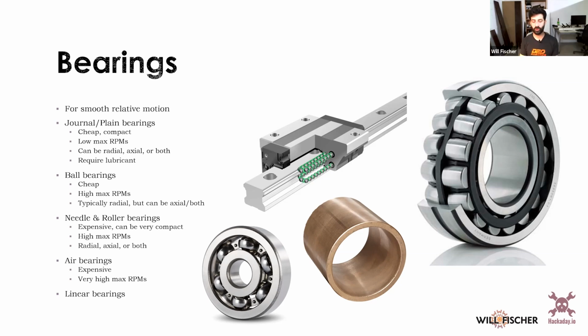You can also get these things called recirculating linear bearings. They look like this. They slide back and forth. And you can see a cutaway diagram of it there. That allows you to have that nice translational movement without getting rotation on any other axis. So if you have something that's moving along a system, these are a really nice way to do it. And they're not super expensive. I think this one was about 15 euros or dollars. Euros and dollars are about the same these days. Yeah, and so you can see over there on the right hand what the inside of a roller bearing looks like.